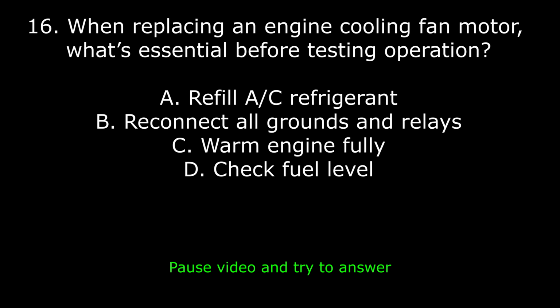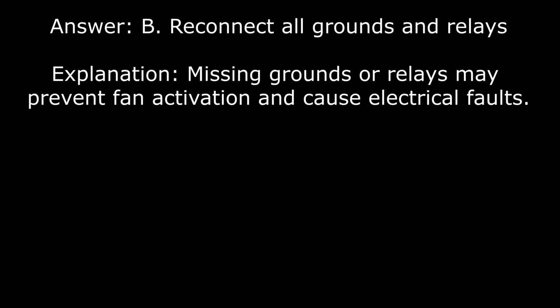16. When replacing an engine cooling fan motor, what's essential before testing operation? A. Refill AC refrigerant. B. Reconnect all grounds and relays. C. Warm engine fully. D. Check fuel level. Answer: B. Reconnect all grounds and relays. Missing grounds or relays may prevent fan activation and cause electrical faults.